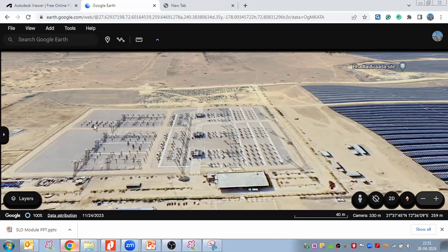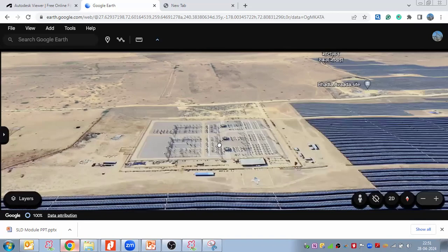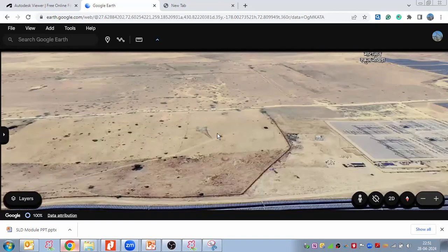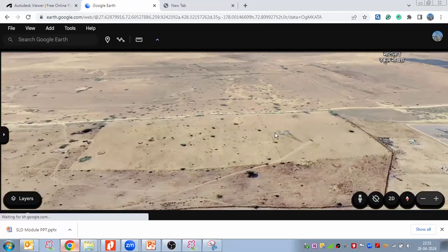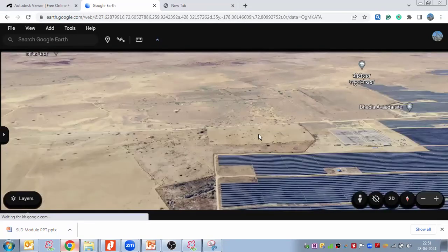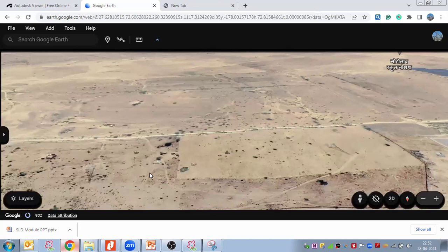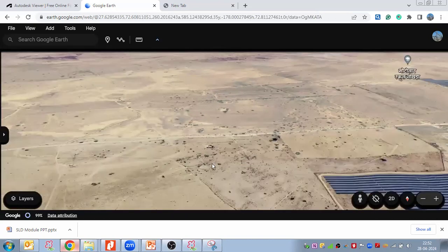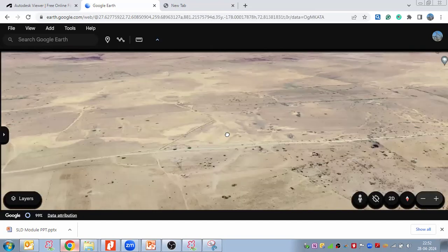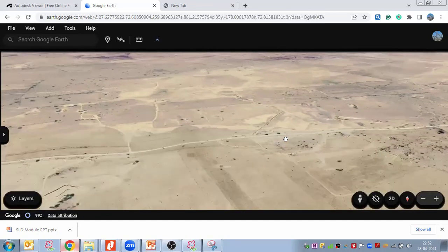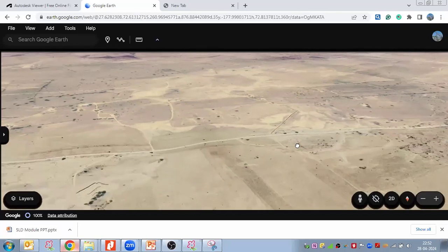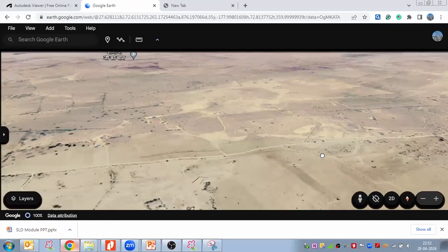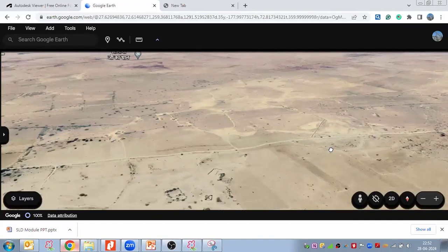So this particular way that you can see, this equipment is extended. Here we have the transmission line. And now if you see, here we have the transmission towers. Tower 1, then you need to spot the next tower where it is coming, next tower over here, next tower over here, and the next tower over here. So this is the route survey to be done, and through that we do the tower spotting through the ROW,